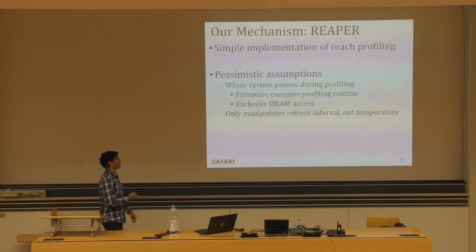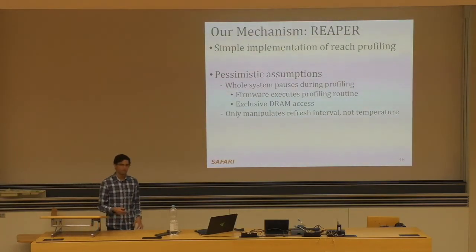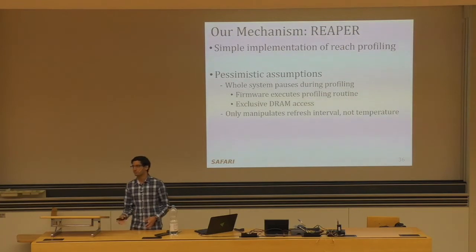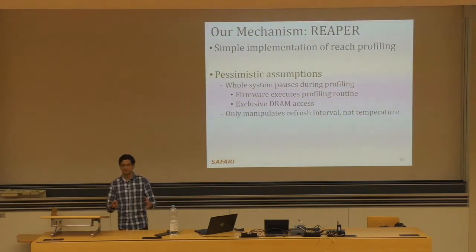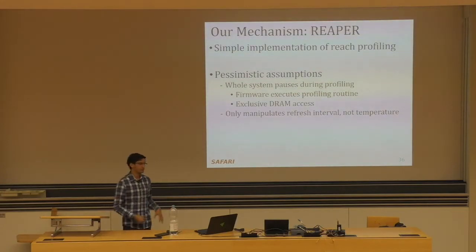The second thing we assume is that the REAPER only manipulates the refresh interval, but not temperature. And we believe this is a reasonable assumption for devices in the field, because controlling temperature, unless you have some lab setup and apparatus, might be a difficult thing to do. Whereas the refresh interval can be controlled potentially just by programming things in the memory controller.